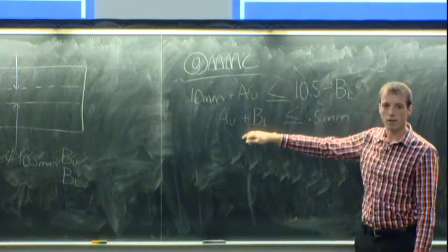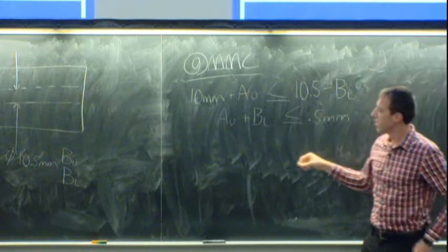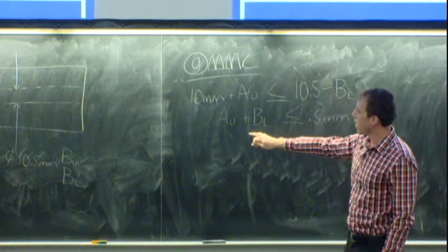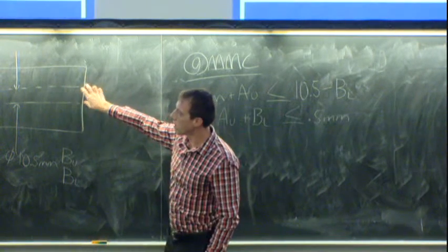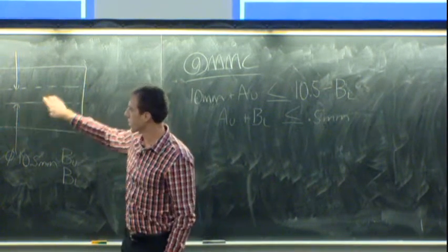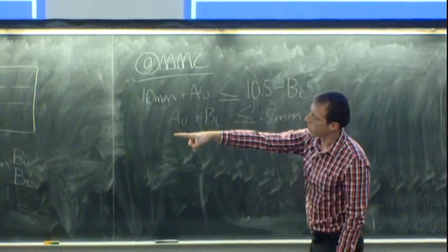So I could set them both to 0.1, but I'm wasting some of my available band. So I'm going to say it's generally easier to hold the tolerance of a hole than the tolerance of a shaft, because you're drilling a hole and you're turning a shaft on a lathe. So I'm going to give myself more room on the shaft.